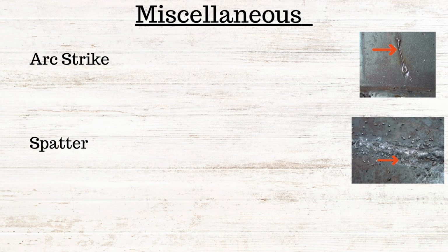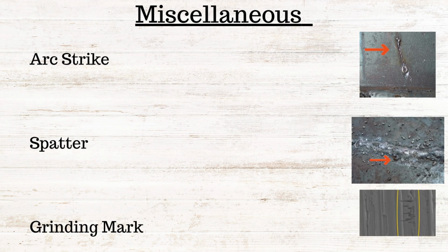There are examples of torn surfaces also, where there is surface damage due to the removal by fracture of a temporary welded attachment. Grinding marks: many times we have seen the welder does some grinding on the parent material, so they are also local damage to the surface. There are some chipping marks also observed as a deficiency or defect. They are the local damage due to the use of chisel or other tools. You can see in the photographs various examples, right?